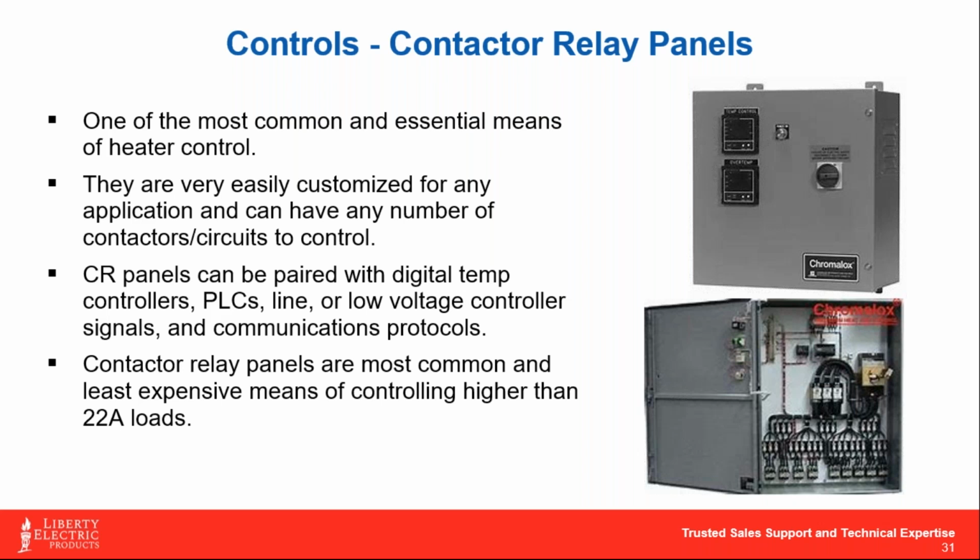As soon as the thermocouple or RTD comes back with that signal, the contactors close, allow power to pass to your heater, and you're heating up your process. So these are very straightforward controls that are quite easy to design. They're affordable and very effective.